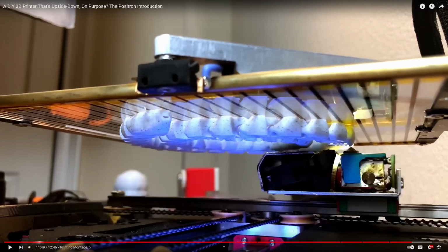You see here also he's got live wires to the face of this guy. So if you grab onto this plate of glass here, if you grab onto the edges, you're going to get a nice shock. If it's unplugged or something, then you might have a lower resistance from one side to another. So you have also exposed things here. This should be coated so that it won't allow you to touch it.